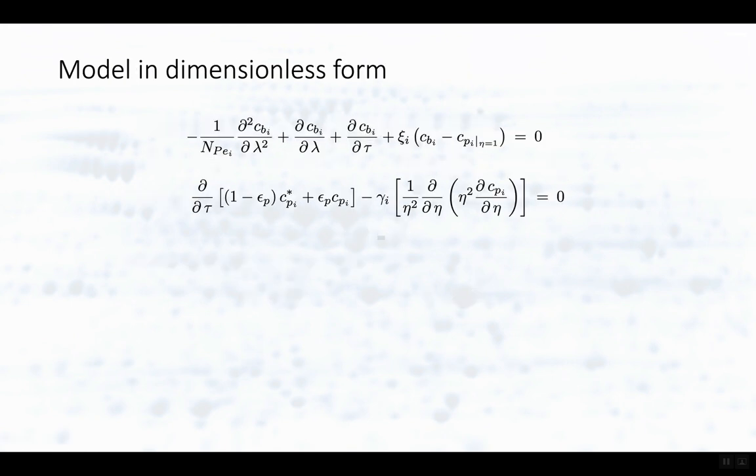So we're doing a dimensional analysis, plug that in, and we find we can rewrite these models. There's actually 2 here. They have to be solved simultaneously. So this is our model for the bulk material moving through the capillary, and in dimensionless terms, some dimensionless numbers come out of this. And this is our model for the pores of the packing. We've got to solve both of these simultaneously in order to solve the problem. So that generates a number of initial and boundary conditions.